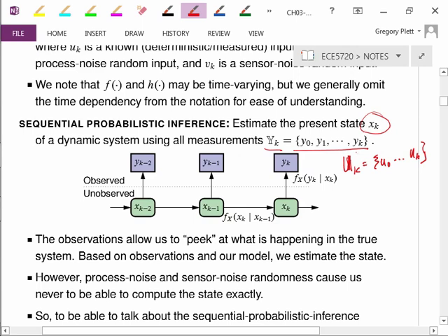How does the state move? Well, the deterministic input u is part of it, but the process noise wk is also part of it. And wk is not deterministic. I can't measure it. I don't know it. It's unknown. It's random in that sense that I don't know it. So because I don't know it, but I want to describe it as an engineer, what do we do? We try to describe what we don't know.